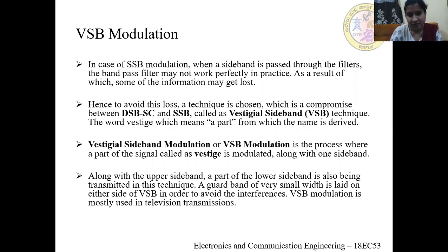VSB modulation. See, SSB modulation is not an appropriate way of modulation when the message signal contains significant components at extremely low frequencies. Because in such cases, the upper and the lower side bands meet at the carrier frequency and it is difficult to isolate one sideband. To overcome this difficulty, the modulation technique known as vestigial sideband modulation is used.